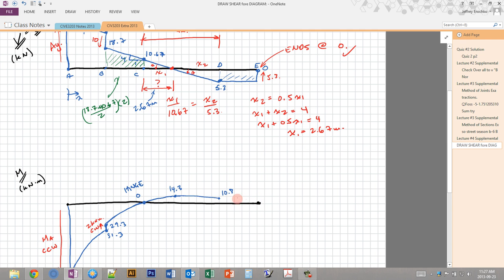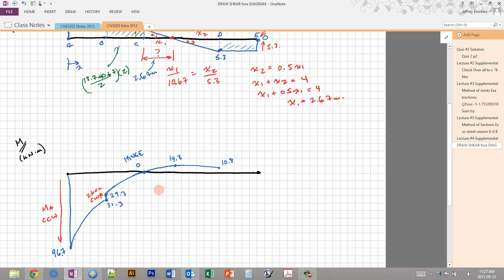Now, what I really should do is maybe keep a few extra digits in your values as you're going through the construction of the moment diagram. So instead of just using 3 significant figures, use 4 or use 5, and then by the time you get to the end, everything should add up. And then when you're asked to quote the numbers, just make sure to quote them in the appropriate amount of significant figures. So when you draw your final moment diagram, you're probably going to want to just use the 3 or the 3.5.